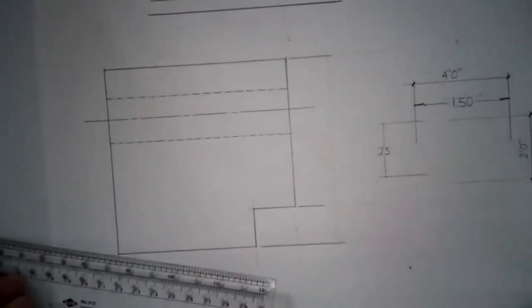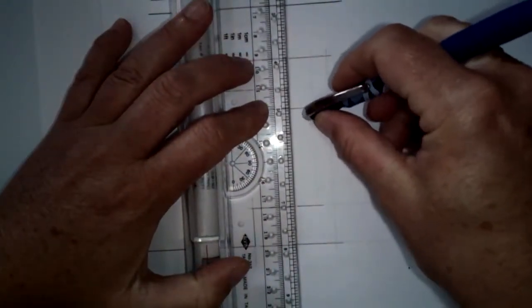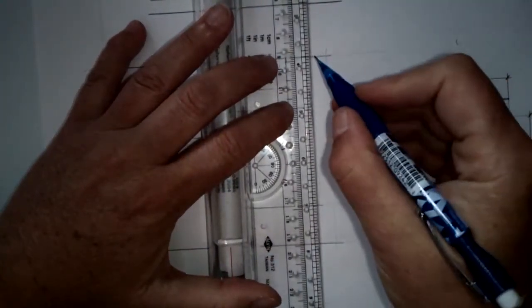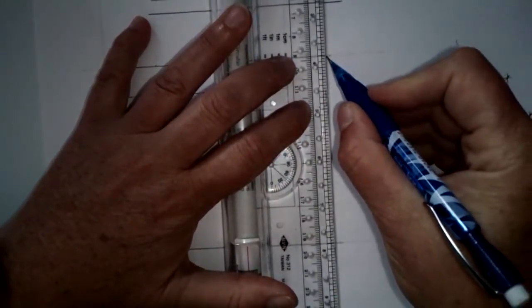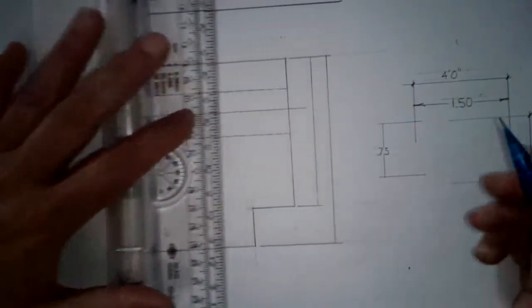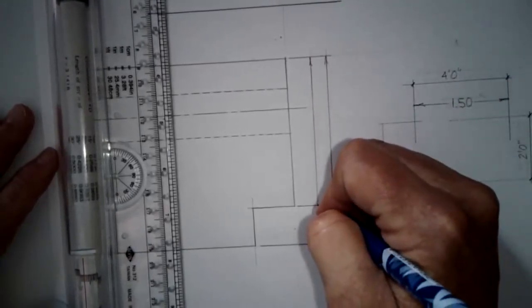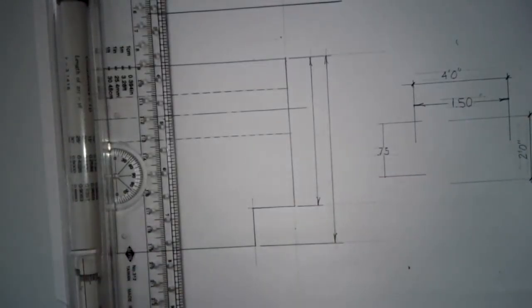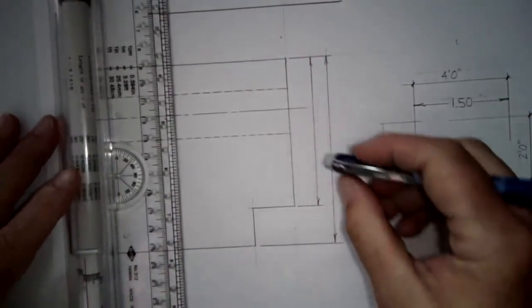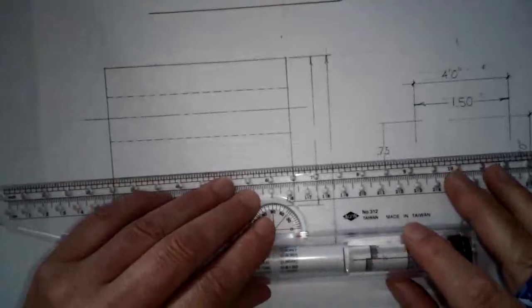So we're calling this a mechanical drawing, certainly. So these are going to be, I'm just going to pull that center line back a little bit. These are going to be our dimension lines that just touch the inside of those extension lines. They don't extend past. Put those arrows in there. Do not bother to fill in these arrows. They never look good when you do that. So just do what I'm doing here, which is creating the little arrows. And then you're going to erase out the middle.